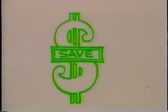Inlet vanes save some power, while discharge dampers throttling at the fan save little. From a first cost standpoint, dampers are the least costly. Inlet vanes and blade pitch control follow, with variable speed motors being the most expensive.